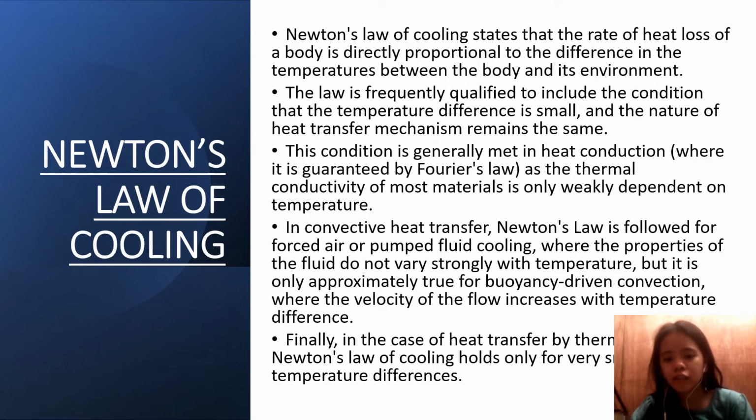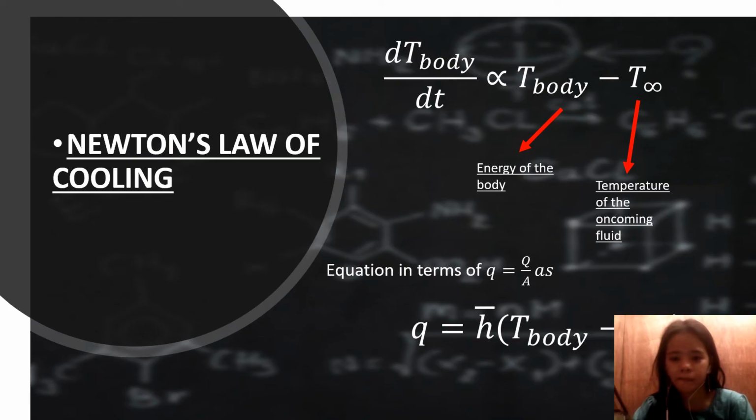In convective heat transfer, Newton's law is followed for forced air and fluid cooling, where the properties of fluids do not vary strongly with temperature, and it's only approximately true for buoyancy-driven convection, where the velocity of the flow increases with temperature difference. Finally, in the case of heat transfer by radiation, Newton's law of cooling holds only for very small temperature differences.